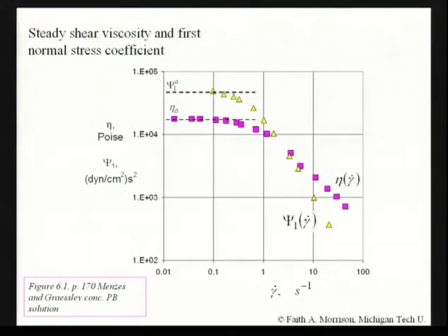So it's not a constant, which says it's a non-Newtonian fluid. And we define a couple of things about these curves when we talk about them. One is that there's a zero shear plateau, it's called. These are lower and lower shear rates. And so at the limit, as the shear rate gets lower, it hits a plateau very often, and that's called eta naught.